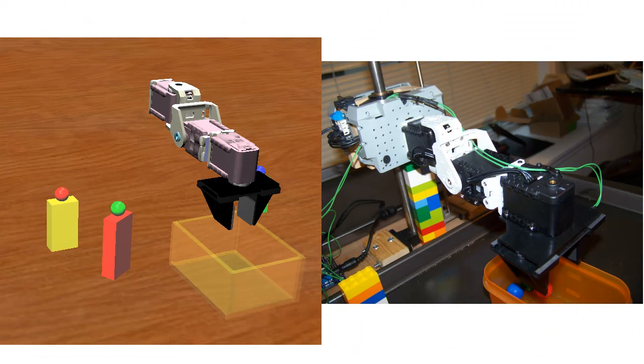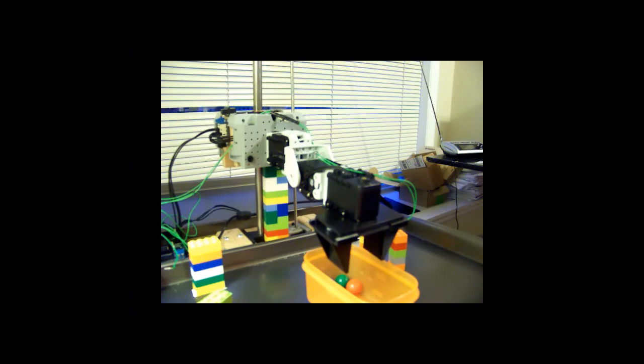Here is a side-by-side comparison of the real robot and the simulated one. The basic simulation is a 3 degree of freedom robot arm. It's pretty limited in its mobility since I wanted to keep this as simple as possible, but yet still have something interesting enough to show how it works. The first joint, the thorax coxa joint, will promote and remote an arm along the horizontal plane. The second joint, the femur tibia, will elevate and depress the arm, while the final joint will be a gripper or a pincher that will be used to grab objects. The gripper also has a contact sensor on it that detects when it's gripping an object.